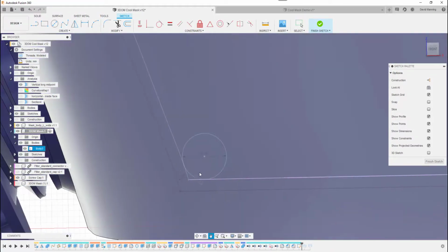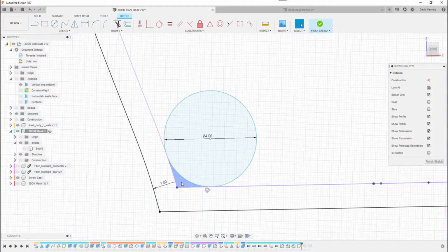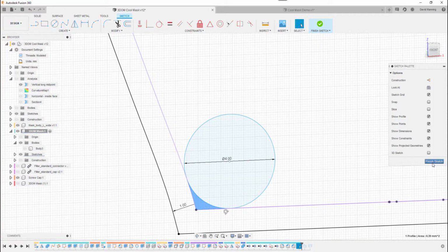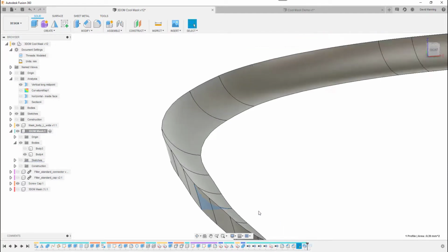So coming back over here, I've just drawn these lines. These are not straight lines, they're all spline because it's a face. So it's very difficult. I couldn't even make that tangent for some reason. I just thought a 4mm radius worked well, so I put in that radius, made sure that it interfered, and if I turn that body off, you'll see there I was able to get a region by making sure that this, while it's very close, is not actually tangent, it actually goes across the line, but it'll do, and the rest of the software will manage it. The other half of this is really fairly easy. I turn that off, and the next step is I'm going to use it as a sweep.